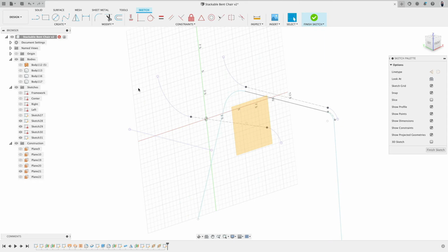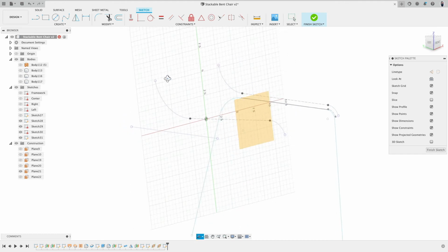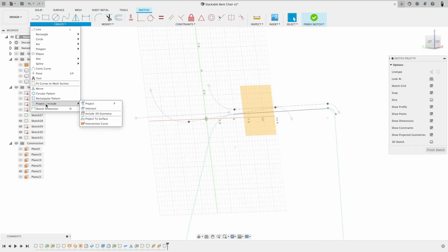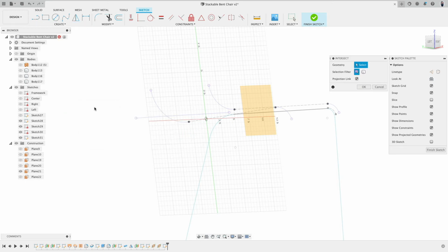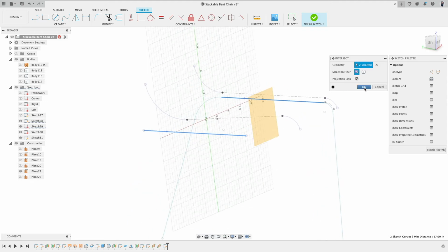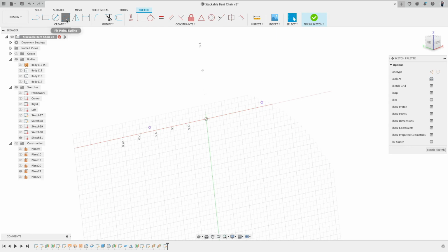Here now I would like to create myself a nice C. So you see where actually this line is and this line. And I need to find a point where this line touches the grid. So this might actually sound kind of complicated, but think about it. All we do is work in two-dimensional sketches or planes, and how do they intersect? So where does this line and where does this other sister or brother line intersect this new sketch? There we are. So there I have these 2 points. And you see? Very good. And now I can go ahead and say, cool, from there to here to there, draw myself this curve.